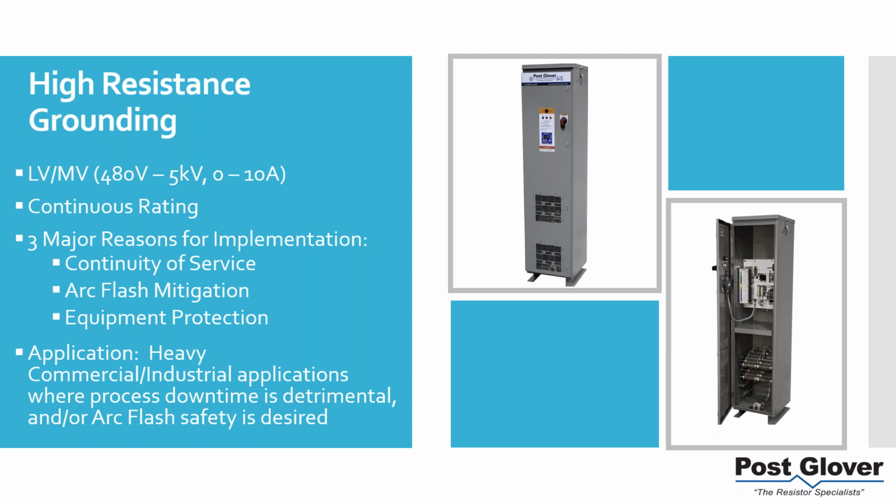The newer one, I would say, is arc flash mitigation. You have a situation where the amount of current flowing is very low at low voltage. Think about a 480 volt system at 277 volts. You have, you know, a 5 amp system typically as your default. For a high resistance ground system, that's a little over 1,000 watts of energy. You also have some voltage drop across that resistor, so you're going down to a fairly low voltage, below where arc flash protection is really needed.